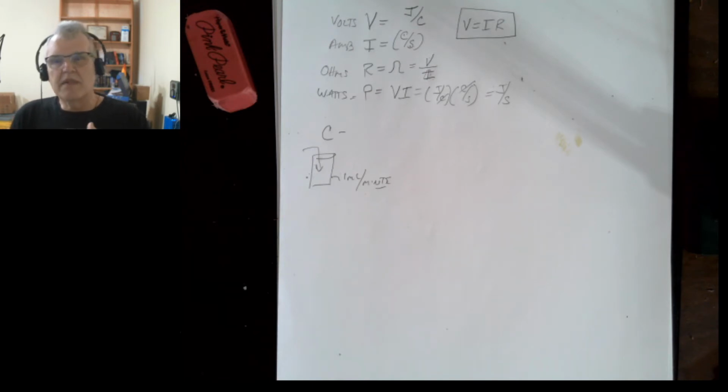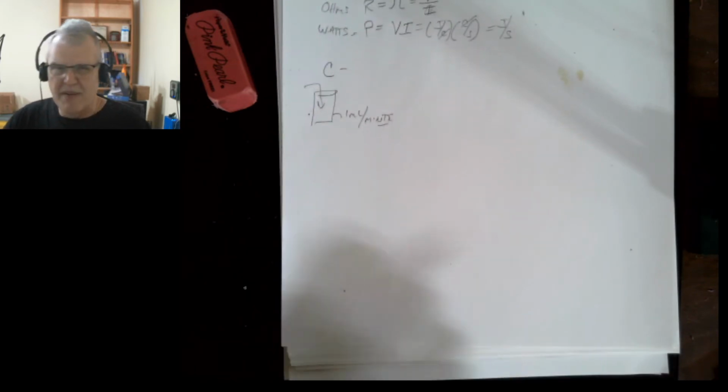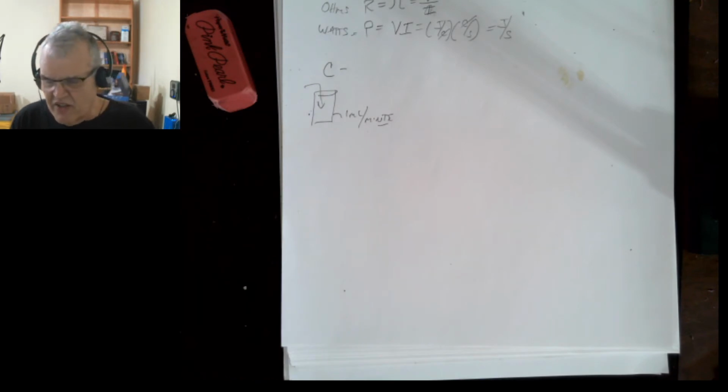A lot of times manufacturers will list the capacities, that's in the amp hours, in terms of a 0.2 C. That means that they are charging it at 1/5 of what the capacity of the battery is listed as. And you'll understand that we get into some other things dealing with state of charge and everything. So, all right, that's the C rating. When you hear about a C rating, sometimes they'll also talk about an E rating, but that's not used nearly as much.